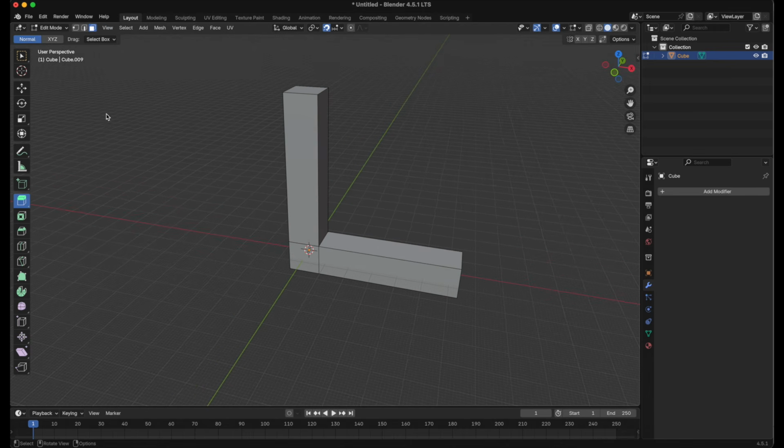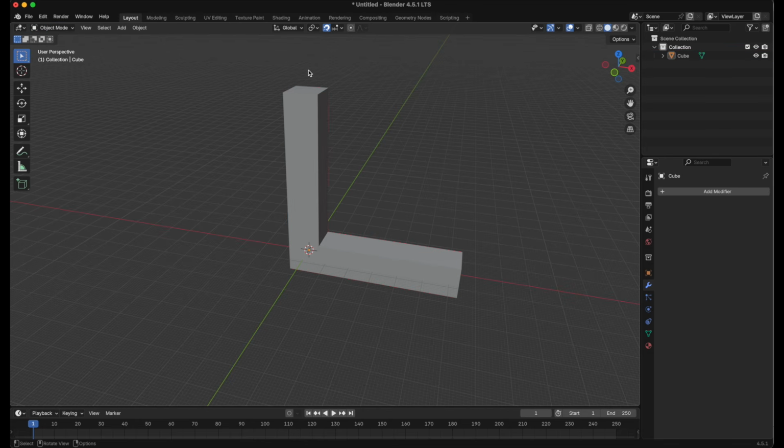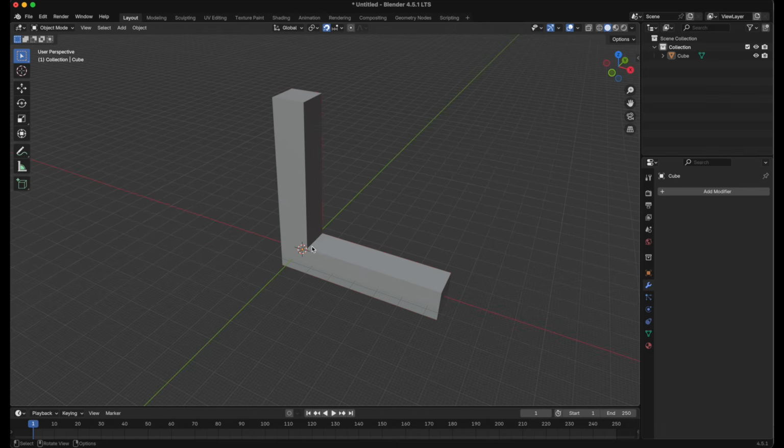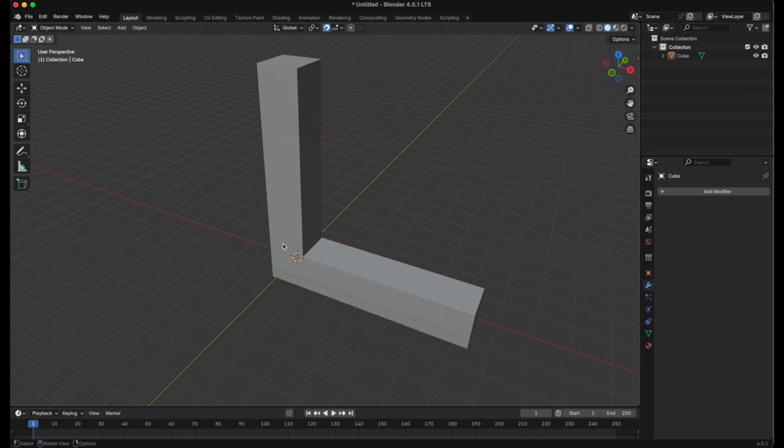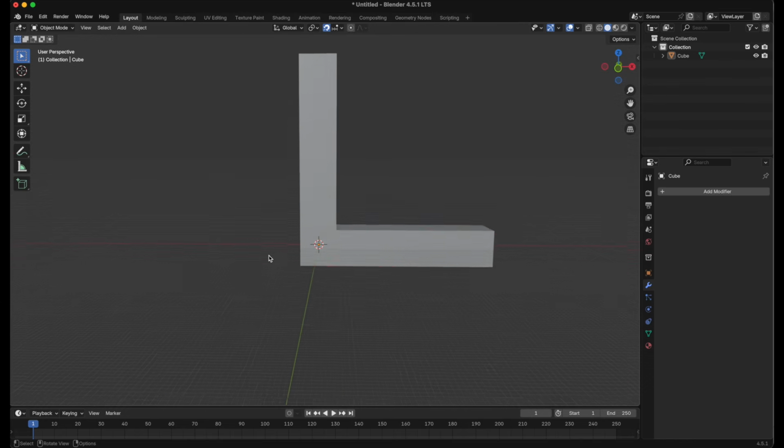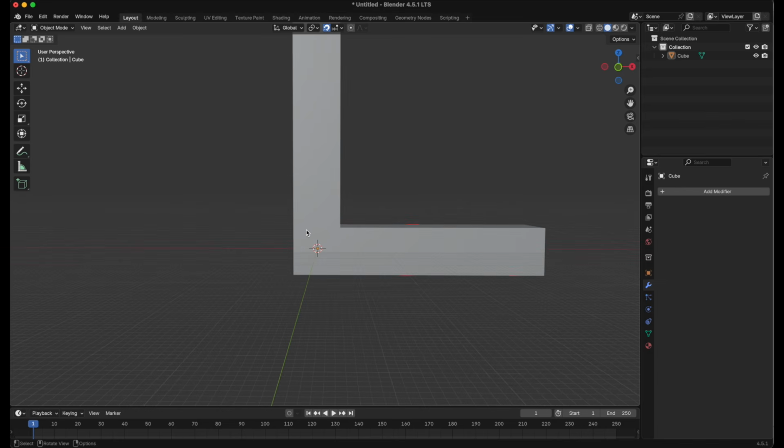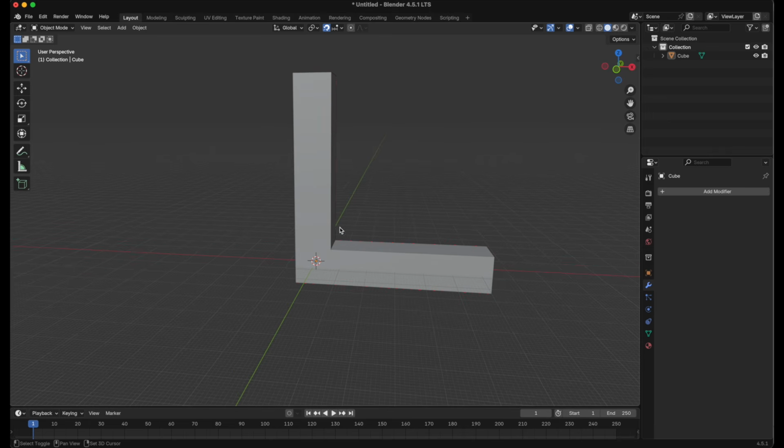In this orientation, it's not optimized for strength because this here is a vertical column and this is a sharp corner, which would add a stress concentration to the layer lines going across here. If you're imagining it printing like so, we have layer lines going across like this, and at this point right here, there's a new layer that starts at this sharp corner. So we have a compounding effect where we have this sharp corner, which is a strong stress concentration, and the layer line, so the part could break right here.